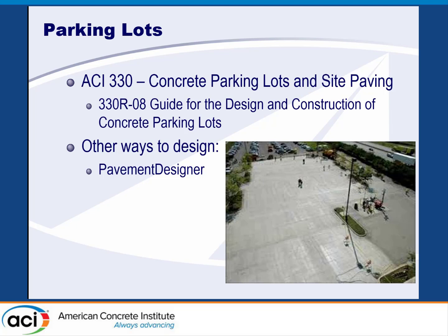So ACI 330 really covers concrete parking lots and site paving. The 330R08 guide, which they're updating right now and which should be pretty close to ballot, covers this design as well. The other thing that really focuses on parking lots is Pavement Designer. Again, Pavement Designer is kind of the all-encompassing tool that can do a lot of this.